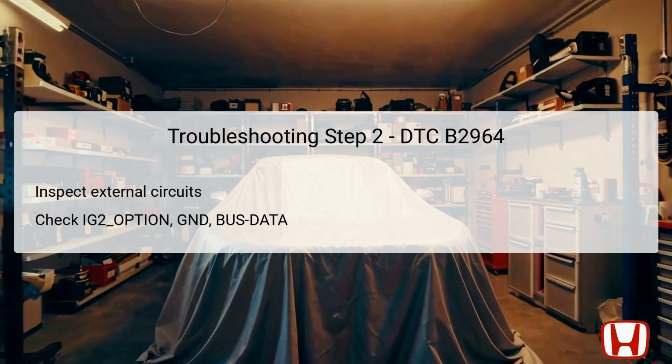Technicians need to ensure that these circuits are free from faults, such as open wires or shorts, particularly focusing on maintaining a battery voltage close to 12 volts for the IG2 option circuit. For an effective diagnosis, it is critical to confirm the resistance values of these circuits. Specifically, there should be less than 1 ohm for open wire inspections and more than 1 mega ohm for shorts to ground. Failure to identify issues in these circuits can lead to recurring faults in the climate control system.